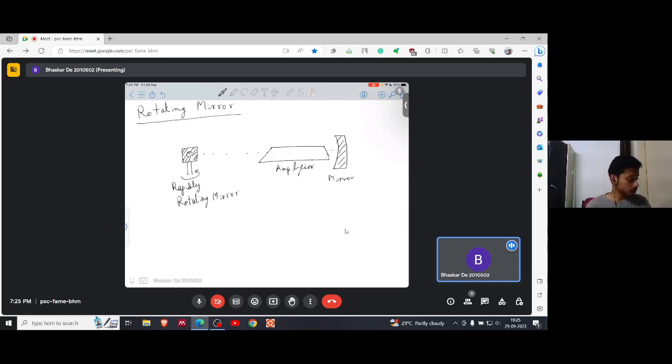It is a hexagonal shaped mirror on a rotating shaft, aligning the facets of the mirror with the laser cavity such that for every sixth of a rotation of the shaft, a mirror would be aligned with the laser cavity, as shown in this figure.